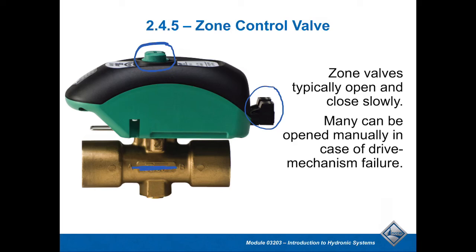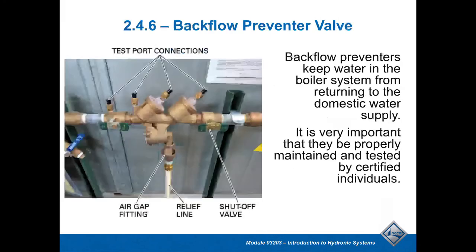The other advantage that I like on some of these is they have a very high CV. So for example, on a lot of my systems, if I want a high CV, if it's a two-position system, I can control my water flow very effectively.